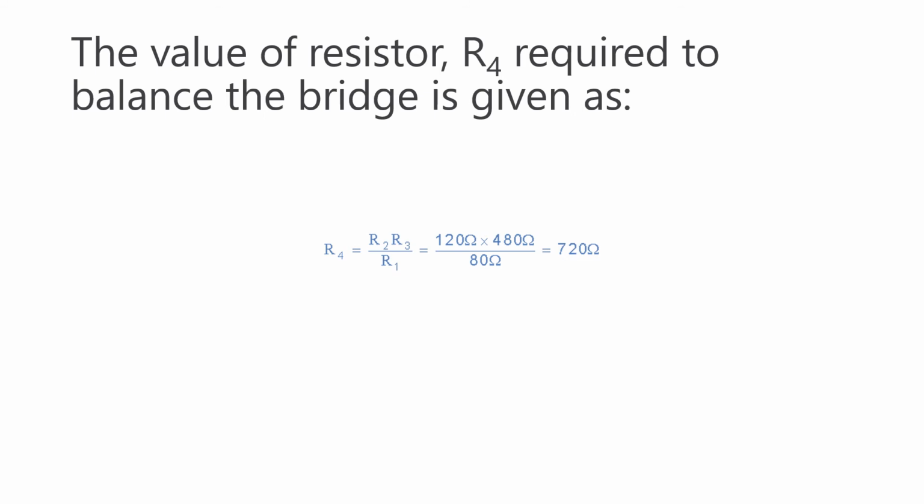The bridge circuit compares the values of the unknown components with that of an accurately known standard component. The accuracy depends upon the bridge components and not on the null indicator. Hence, a high degree of accuracy can be obtained by using bridges for the measurement of the component values.